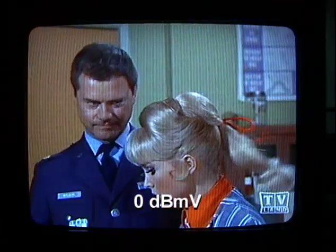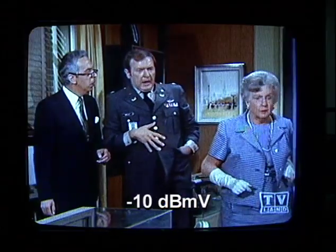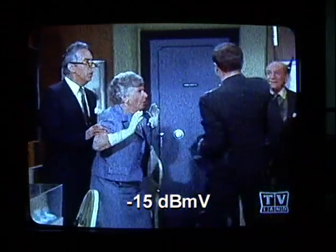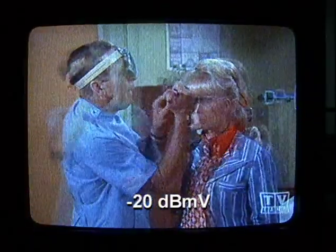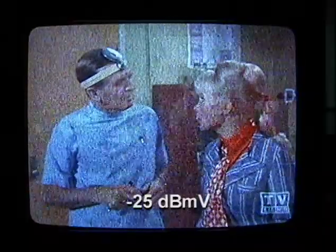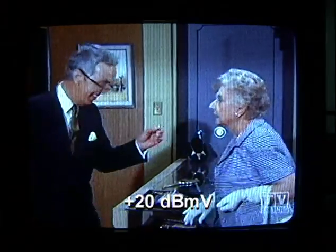This is also the range that the cable tuners in televisions are designed to handle. When the signal level drops below minus 10 dBmV on a particular channel, the picture will begin to show noise, commonly referred to as snow. This is minus 15 dBmV, minus 20 dBmV, and minus 25 dBmV. Not so good. When the signal level exceeds plus 15 dBmV, the picture will begin to exhibit a noisy herringbone